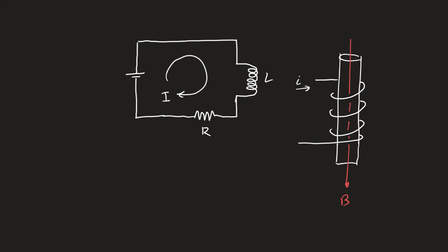So be aware, although an inductor technically will have no effect on your circuit at the steady state condition, it's going to dissipate energy as heat just like any resistor. And there's no way around it. So it's hard to build the inductor circuits that we're supposed to test out, considering that they add resistance to the circuit in a manner that's difficult for us to manage.